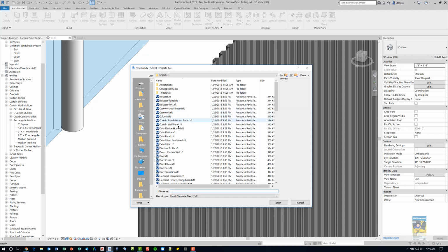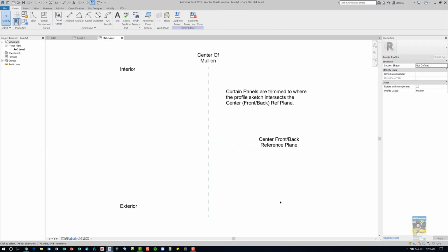Here, you want a curtain wall mullion profile. If we head down to Profiles, you'll see there's one called Profile Mullion A. You can even see from the preview that it looks just like the one I did earlier. If I click Open, then it gives this to you, and I can load in, insert, or draw from scratch the profile that I want for that panel.